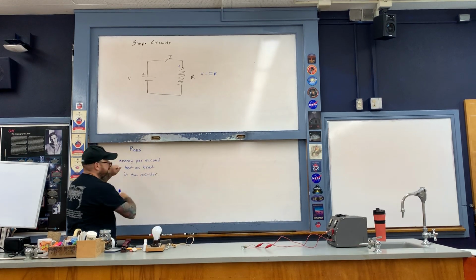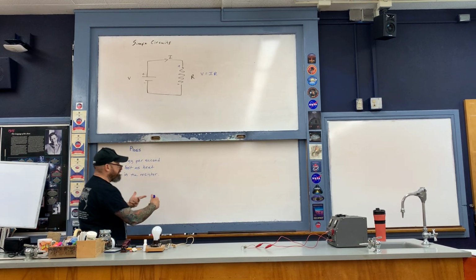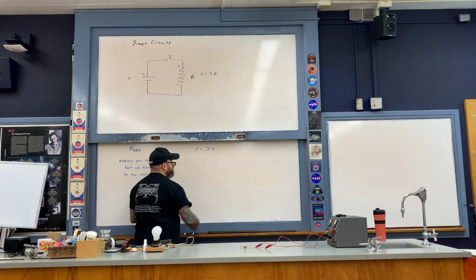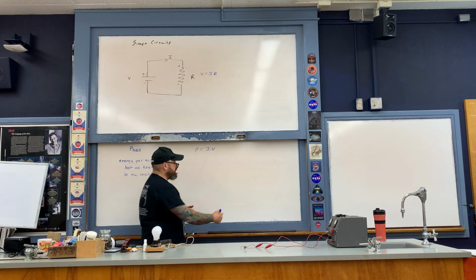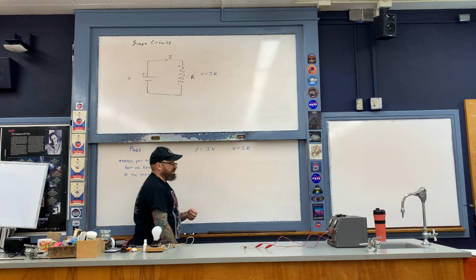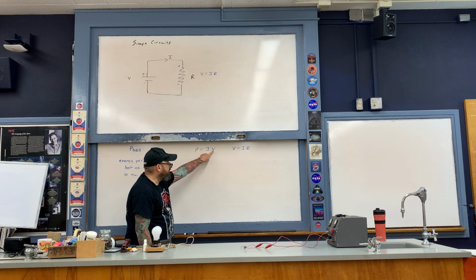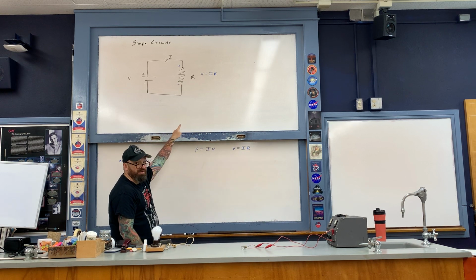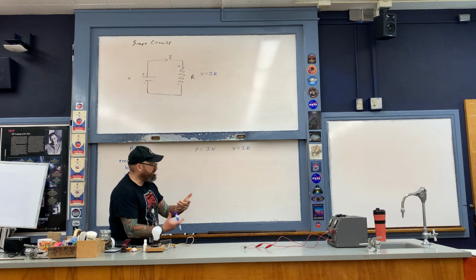Okay, so now getting back to this calculation, P loss, we're going to combine together two things. First of all, from earlier, the power delivered by the battery is equal to I times V, and V is equal to I times R. Go ahead and first of all replace the V here with I times R from the diagram above. When you do, you end up with the following.